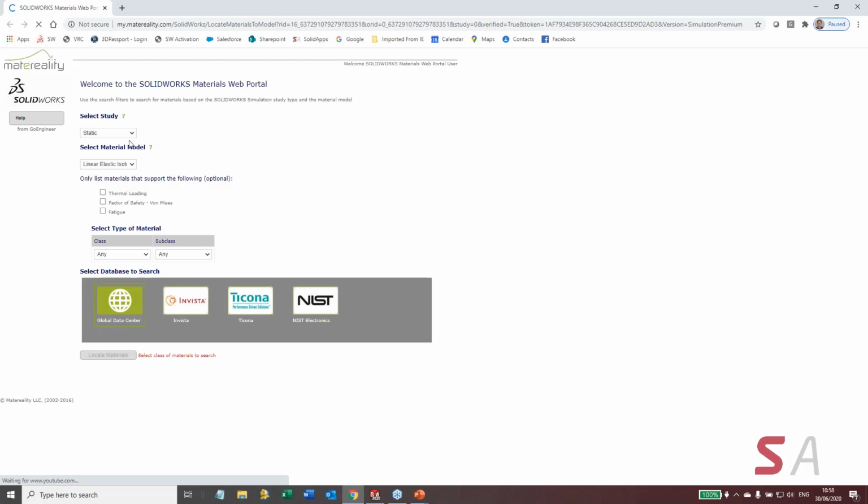I was a little reluctant to show it to you because my experience is when I chase down materials here, my success on these 4 databases is spotty. Sometimes I'll be looking for a particular kind of plastic and I'll just come up with a complete treasure trove of all different types of that plastic. And other times it's a complete goose egg on all 4 databases. So you'd be wanting to look, for the most part, if you're just running linear static studies with linear static isotropic material, in the classes of a particular kind of metal or plastic or rubber.